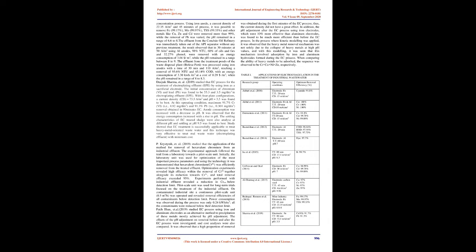Amira Dagaz et al., 2019, investigated the EC process for the removal of divalent iron and zinc cations from water with aluminum electrodes in a discontinuous system, and the effect of hydrocarbonate HCO3 ion, frequently present in liquid waste and in groundwater, on the EC process. For these 2 ions, the presence of hydrocarbonate strongly limits the pH variations by its buffering properties and reduces the rates of Al dissolution by corrosion. Removal of these 2 cations was then shown to need longer treatment times and larger amounts of dissolved aluminum.